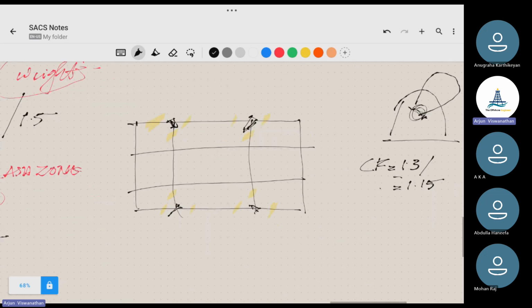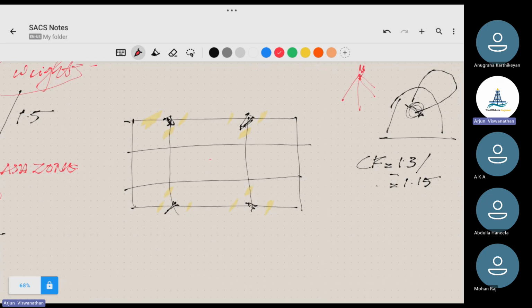So now let's say this was my plan view, and I am going to connect the slings. There will be a hook point, and I will have slings going from that hook point. Now let's say this is my COG, the geometric center, and we will always make sure the hook point correctly matches with the weight COG, not the geometric COG.